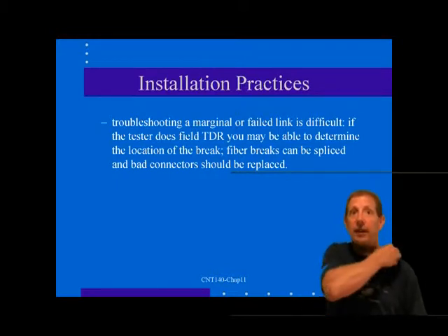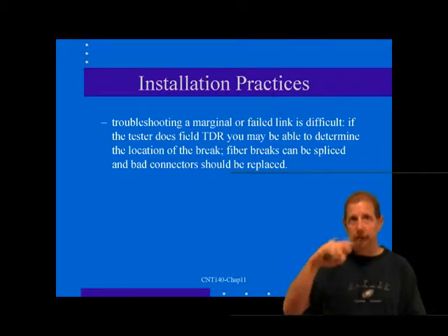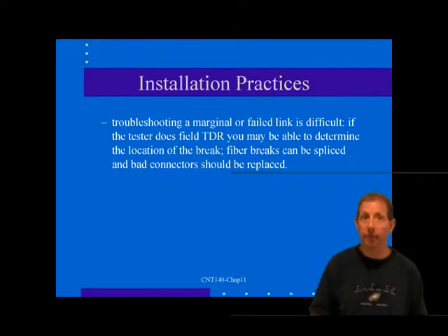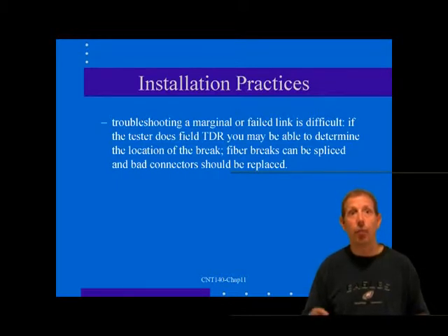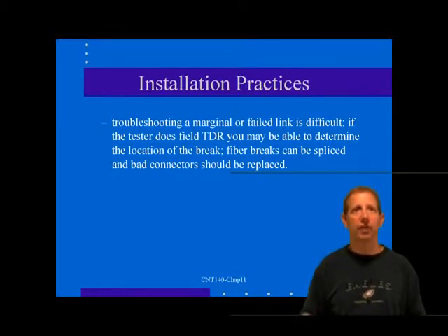Testing installed fiber cable is a matter of measuring the link loss. In general, if the link loss is within budget for the standard, and with stricter link budgets for certain applications, your cable is fine. You should really test all the appropriate wavelengths for the application, and the tester should use time domain reflectometry, or a TDR, to ensure that the cable length is within the prescribed length for its distances. Some more sophisticated testers may ensure that return losses, a measure of reflections, are within the limits. But if you use appropriate cable and connectors, that should not be a problem.